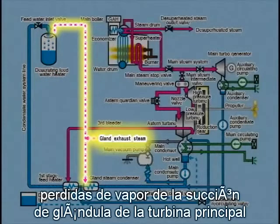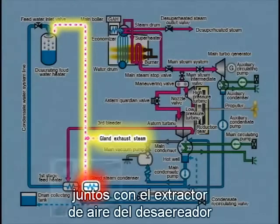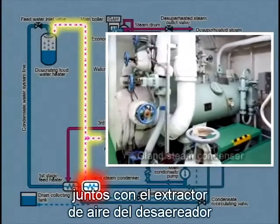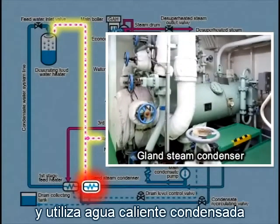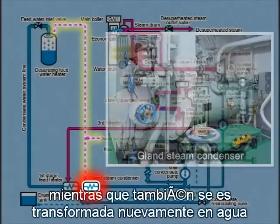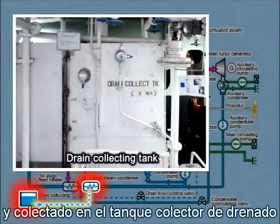Leak-off steam from gland sections of the main engine turbine and other units is called gland exhaust. Together with air extracted from the deaerator, the gland exhaust is guided into the gland condenser and used to heat condensate water, while also being transformed back into water and collected in the drain collecting tank.